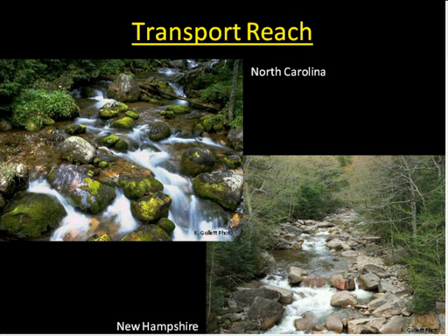So stream crossings in these systems need to be steeply sloped and able to pass basically constant and periodically high bed load rates and large pieces of wood. Limited interaction between the river and its floodplain confines most high flow events to the channel margins. Channel changes associated with crossings are usually localized to the area near the crossing itself, extending up and downstream only a few channel widths.